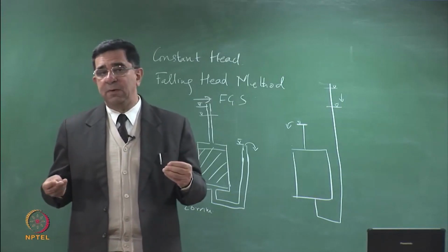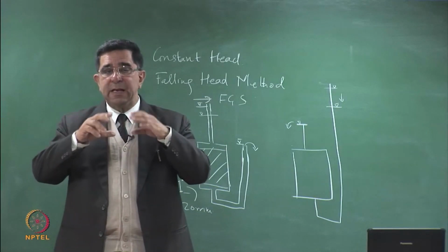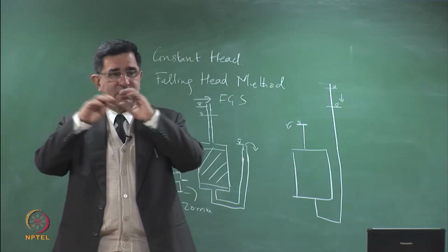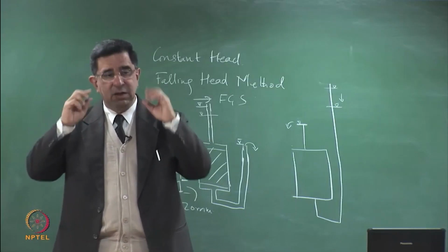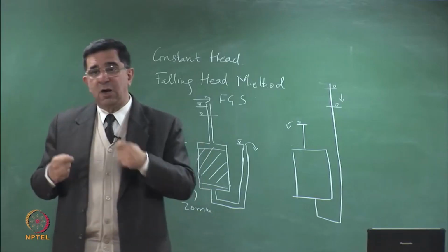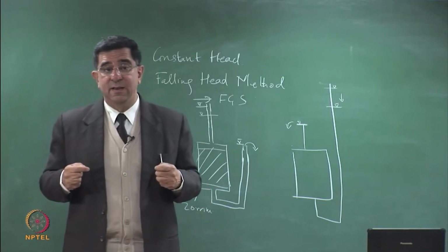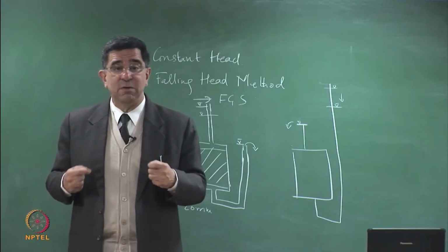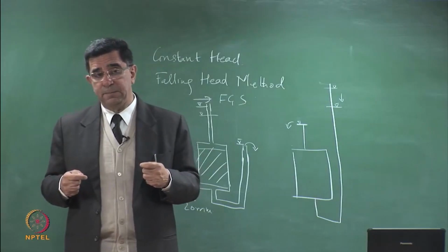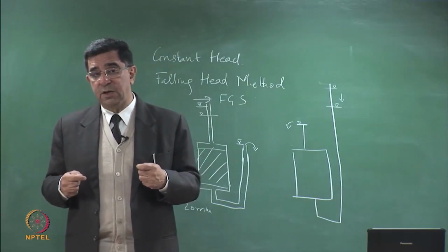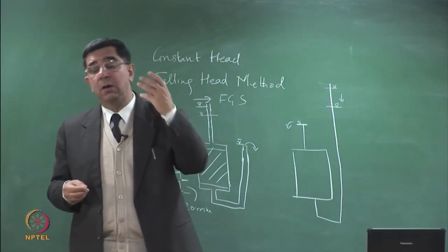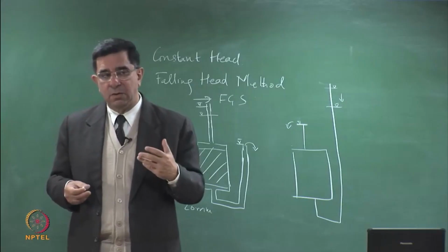So soaking a sample does make the degree of saturation go up, because water is in contact with the lower surface and with the upper surface, and some of the suction, if there is negative pore water pressure, will draw in the water, but does not necessarily saturate it to 100% to get a B factor of 1. For saturating a sample which is in a consolidation ring, you have to have contact with water only on one side and leave it open on the other side so that the air can come out.